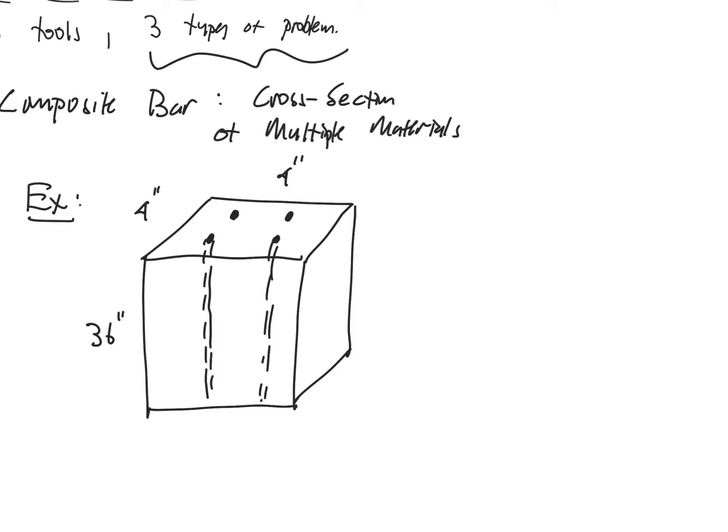So we have concrete with 4 1/2 inch diameter rebar. And this isn't really a great use of rebar. The main reason rebar is used is because, as you'll either have learned already or will learn if you're a civil, concrete is very strong in compression but fairly weak in tension. And so the purpose of the rebar is to strengthen the concrete zones that are in tension. But in this case, we're going to put a block load here of 1,000 pounds.